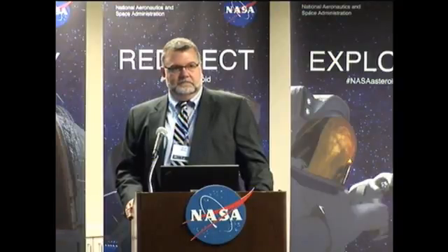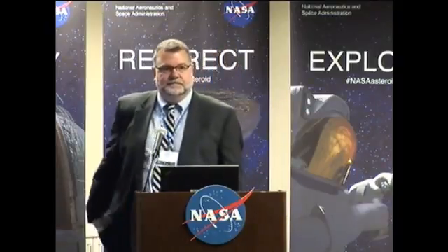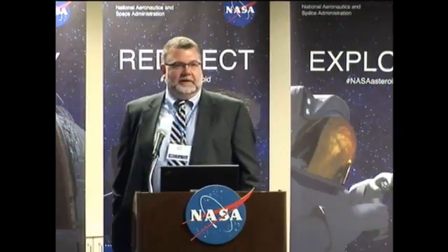I mean, usually you make these booms out of some kind of composite material, and when you do that, you get to a certain point, and all the little booms are going to snap if you get to a certain load point. Sure. Torsionally, especially. Right. So when this thing wraps around itself, the calculation I showed up here was looking at that. That was the first order calculation that we performed.